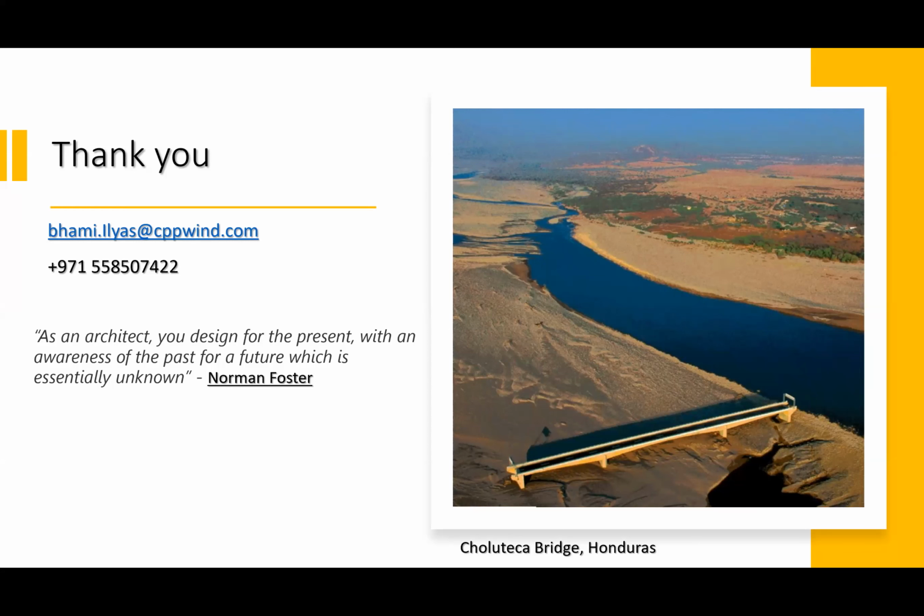Okay, this is another question from Kaiba. How important is it to consider aeroelastic and aerodynamic damping in wind response assessment? It is a very interesting question, because the aerodynamic damping needs to be considered. The damping side of things particularly gets complex when you're talking about high-rise structures, and that's essentially where we're talking. Let's take a step back to see the basics.